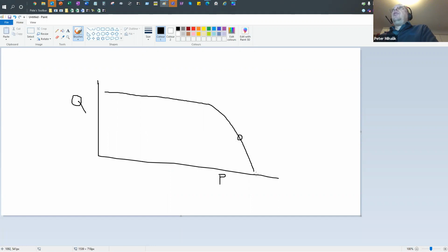What happens if you keep reducing pressure downstream of your choke, the operating point moves upwards according to this curve, but it will eventually flatten out. And then no matter how much you reduce the pressure downstream of the choke, you're not going to get any more fluid rate going through there, because physically you can't fit any more molecules through that space. Okay.